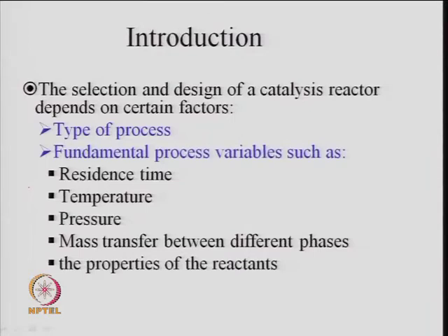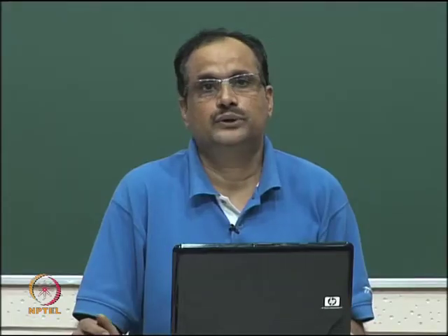Generally, if small scale production is required, then a batch process can be used, but if the production requirement is large, then we need either a CSTR type, which is a tank type reactor, or a tubular, packed bed type reactor, but both are continuous operation. In the batch, the conditions may change inside the reactor with time, so it is a kind of unsteady state reactor, whereas the plug flow or the CSTR are continuous type reactors. If the catalyst does not decay during the reaction, then we expect that the productivity should not change during the course of reaction.